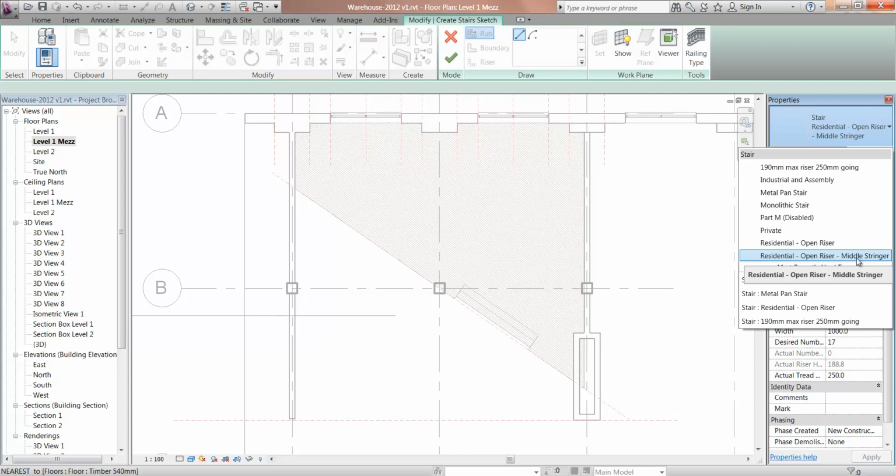And it's important because the last tread is different. In a concrete stair, you don't have that last riser. The floor is your last tread, and so your last tread in the concrete stair is the one below. But in a stringer stair, the stringer has to go all the way to the floor above. So they're a little bit different. That's why maybe at first it's worth avoiding the monolithic stair, because that's a solid stair. All the concrete and monolithic stairs are solid and they're a bit trickier to work with.